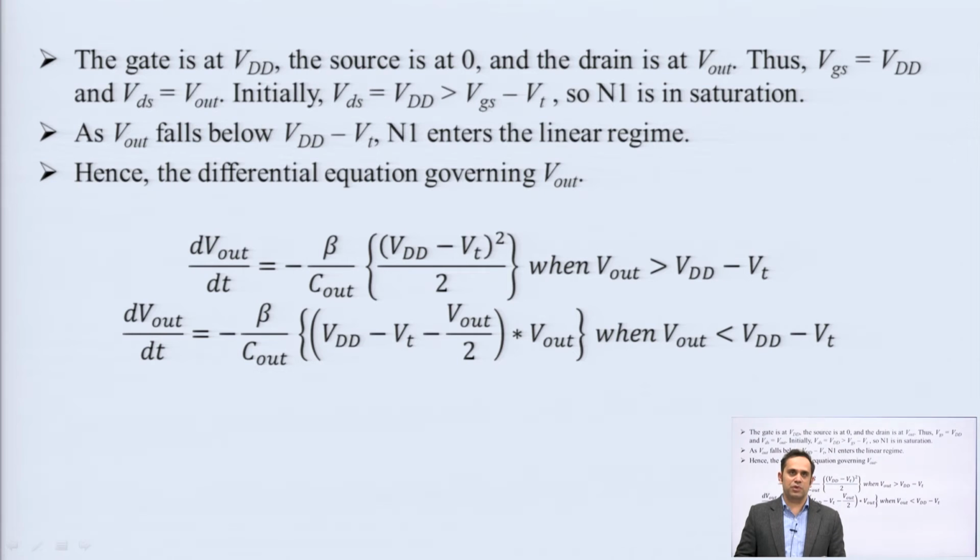If you remember the working of a MOSFET, it is not a linear device; it starts in a linear region and then moves on to saturation. In saturation, the output current is not a function of the drain voltage, but in the linear region the current varies linearly with output voltage. That is also why your MOSFET is considered a voltage controlled current source, because it provides constant current during saturation.